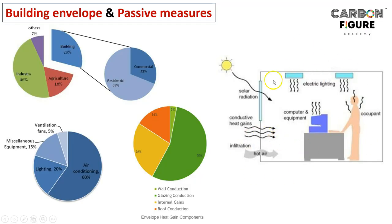Out of these different options, which holds the major proportion? The wall conduction. Not the wall conduction, the glazing conduction, which holds 55%. The next thing is internal gains, which come from electric lighting, computers, and other electrical equipment, and even from the occupants themselves, as some heat exchange would be there.